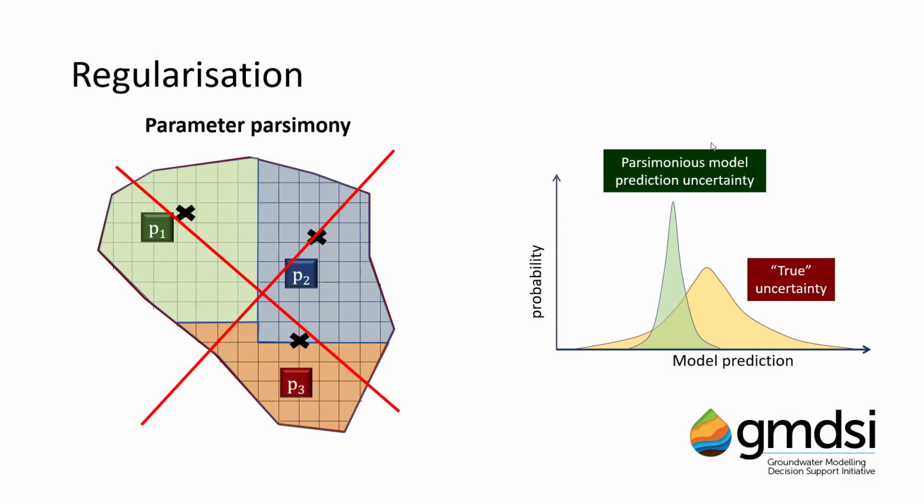Having many parameters does come at a cost. When using derivative-based methods, such as are implemented in PEST and in PEST++ GLM, the computational cost of calibration is proportional to the number of adjustable parameters. Operation of these methods requires carrying out a model run for every adjustable parameter during each iteration of the inversion process.